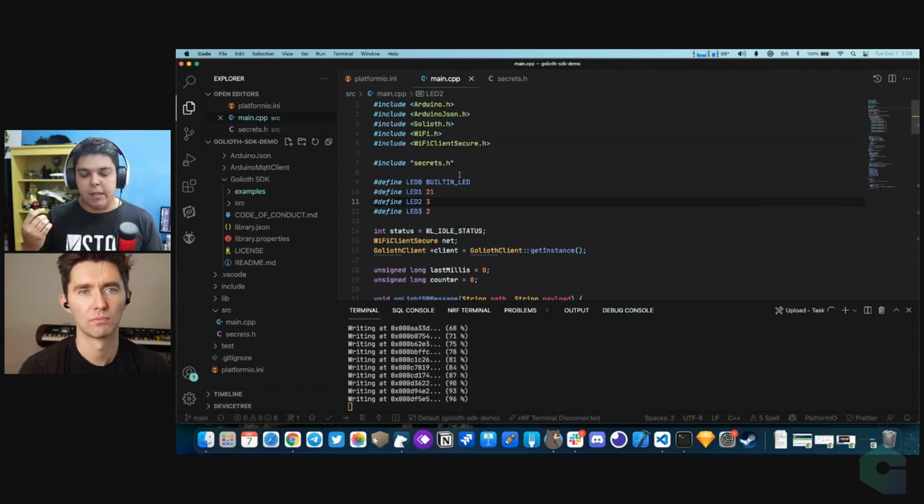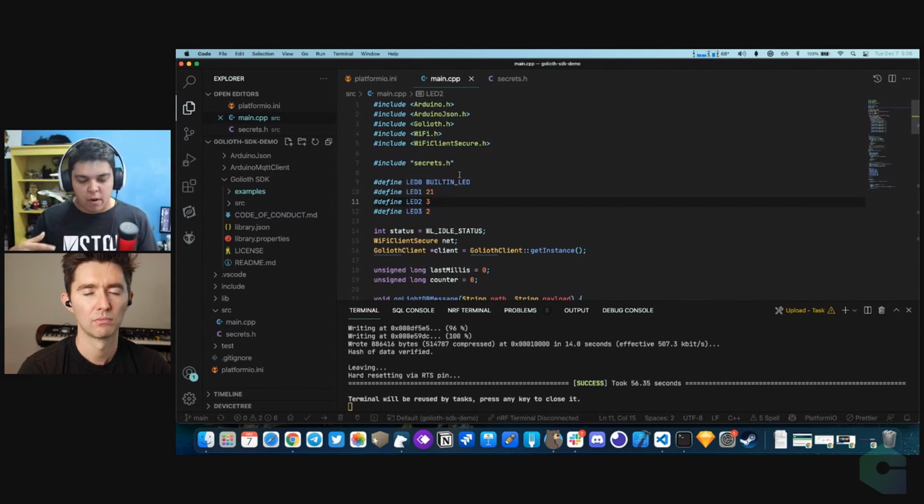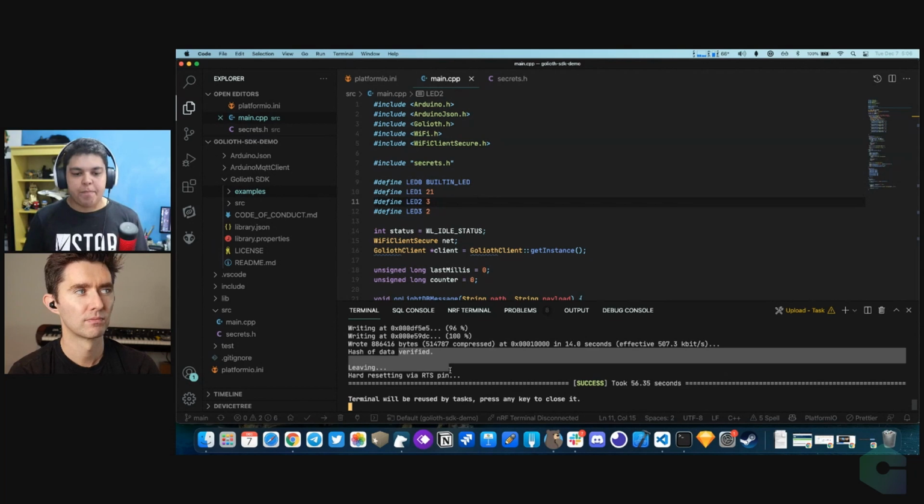They implemented the support for ESP32 in the Arduino Core here. So under the hood, it's downloading the Espressif Arduino Core port and using it to compile and run and support that board. So it's not using any Arduino specific library, but it's implementing their core functionality, like their core API.